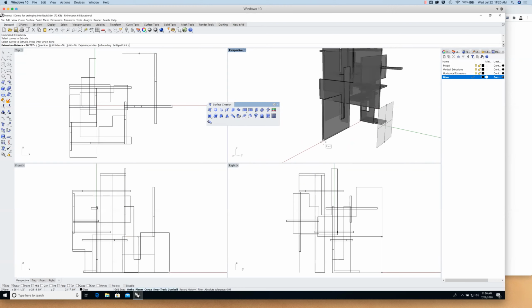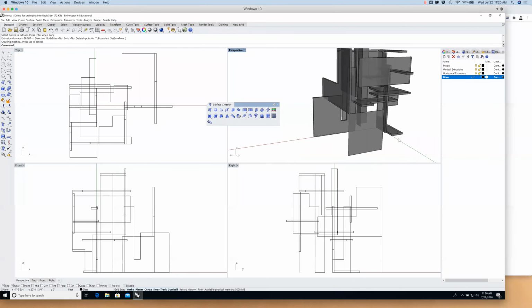I'll go ahead and try to snap to something in that XY plane. Yeah, there we are. Kind of a weird, funky thing, but whatever. Maybe I want to move this. I'm going to move it 4 feet over. That way the mullions have a shot at lining up with this wall, since they're spaced 4 feet on center. 4 feet.